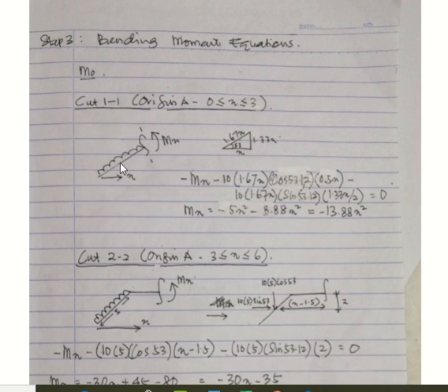This vertical component is a force, and ask yourself where you want to calculate your moment. You want to calculate moment at cutting 1, so you must have this dimension from the force to cutting 1. So the distance is x divided by 2, that's why 0.5x. This is from the force in the vertical component.